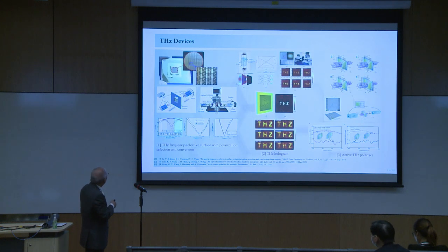Here we have fabricated other terahertz devices. For example, these are the passive polarizers. Depending on the operating frequency, it has different performance. The key thing about this work is that we measure the goodness of the circular polarization. You can see that at the very high frequency of 900 gigahertz, the measurement and simulations overlap. It's very difficult to perform the measurements here.